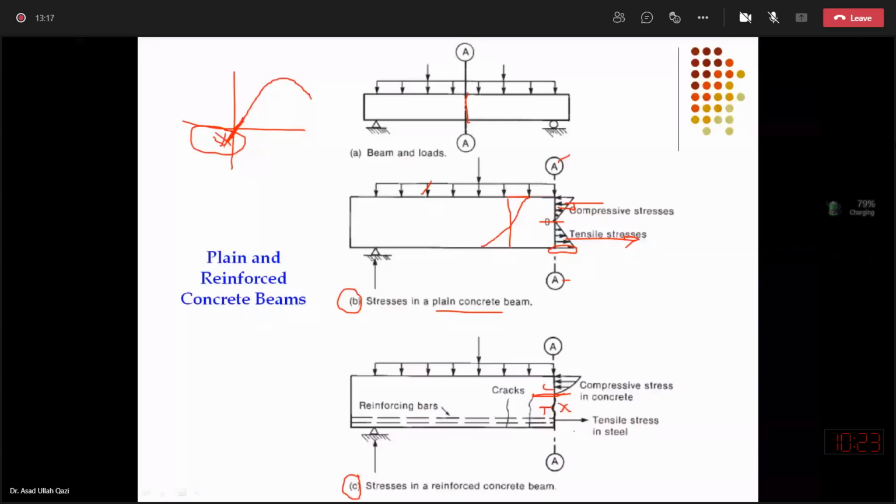is being given by the steel bars, and the concrete's role is to develop the bond between steel and concrete, and it is not allowing the bar to slip, so it is still holding the steel. The cover concrete is still responsible to prevent the slip, deformations on the bars, chemical adhesion between steel and concrete. There are mechanisms which are developing the bond. So composite action is still present, although the role of concrete in tension is negligible at the section level, but its otherwise role is there.